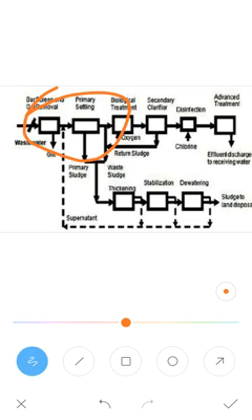Next is the primary treatment process. This treatment process consists of removing the large suspended organic solids, usually achieved by the sedimentation process. The liquid effluent from the primary treatment contains a large amount of suspended organic matter, having a BOD of about 60% of the original. The organic solids separated out in the sedimentation tanks are often stabilized by anaerobic decomposition in the digestion tank. This residue is used in landfilling or soiling conditions.